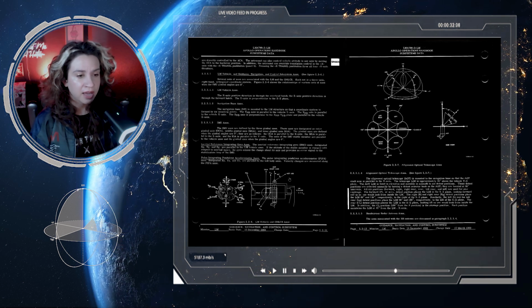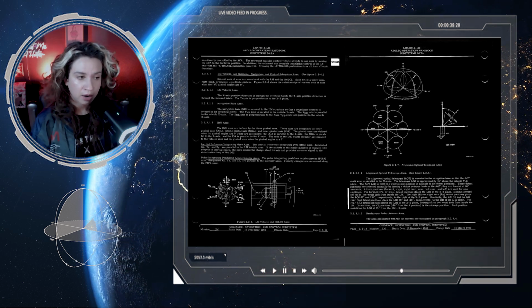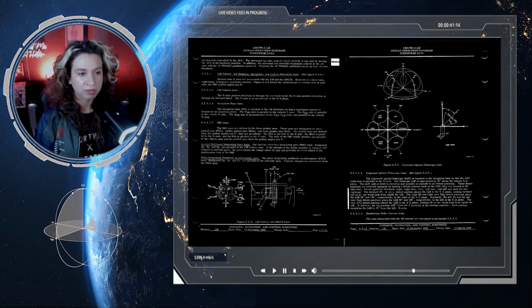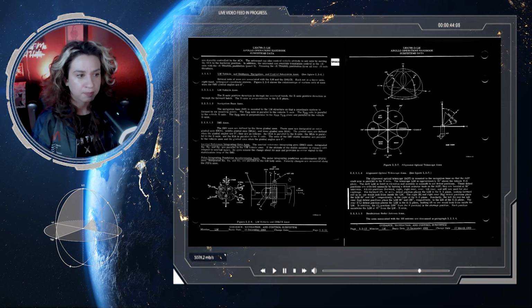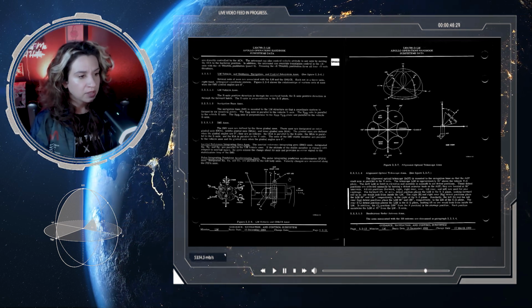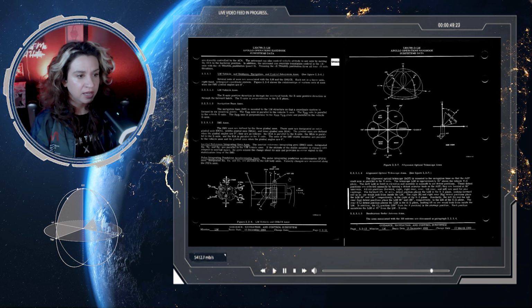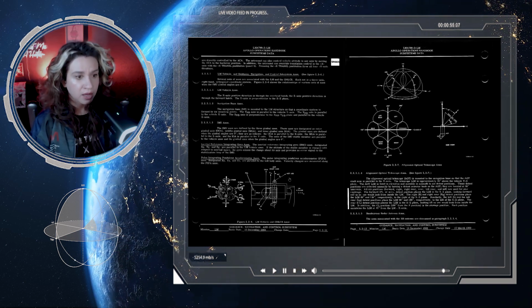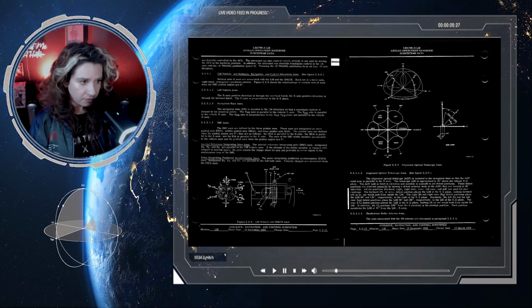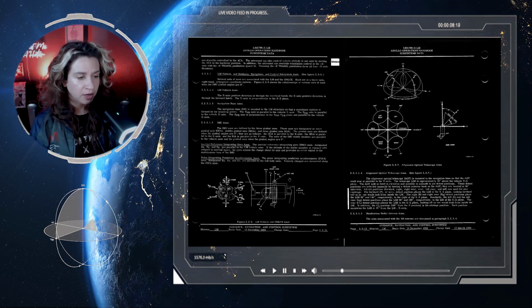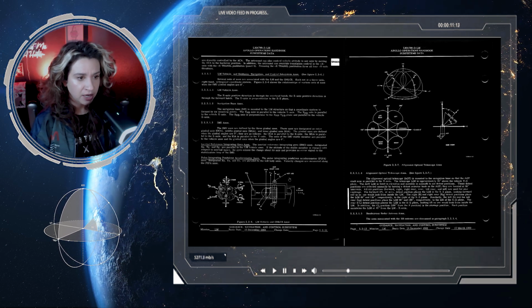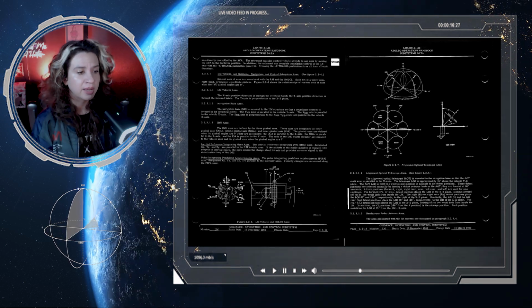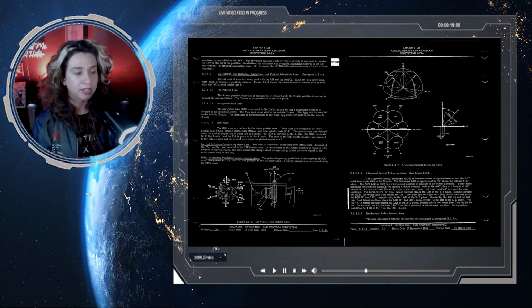Similarly, the left, or L, and the left rear, or LR, detent positions place the LOS at 60 degrees and 120 degrees, respectively, to the left of the XZ plane. The rear, or R, detent position places the LOS in the XZ plane, looking aft as one would look from inside the LM. In addition to the rear position, 180 degrees from the F position, is the stowage position. Each position maintains the LOS at 45 degrees from the LM positive x-axis.